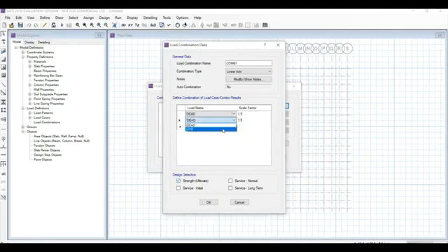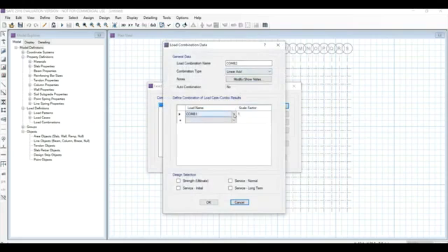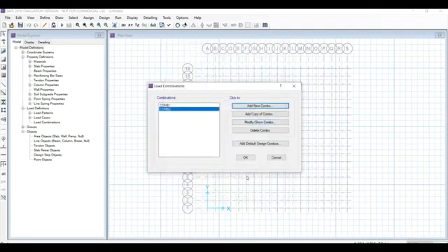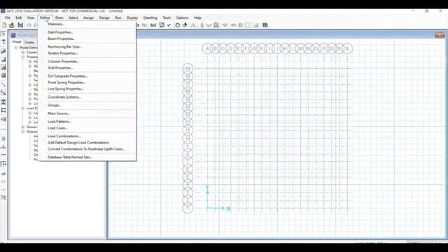Sorry, here we need to change live load, and then click OK. And again add the new combo 2, load live dead load as 1, live load as 1, and check all the service loads condition. That means the normal, initial, and the long term. And then click OK. Two load combinations are being selected, and then click OK. And now for defining, nothing is left.